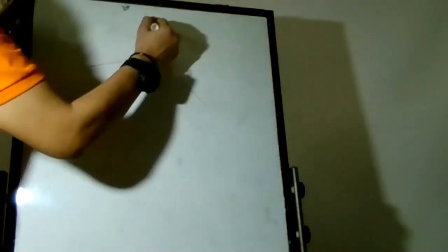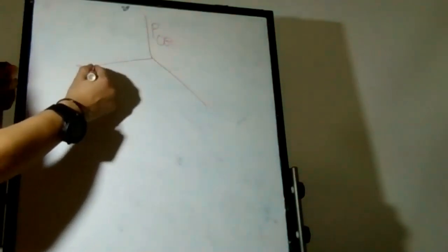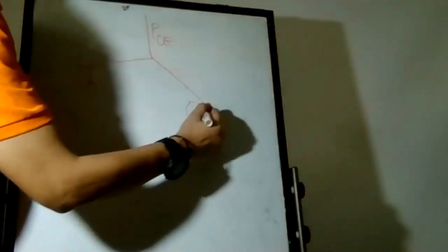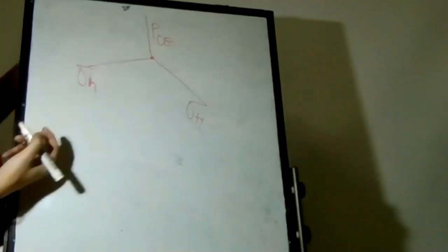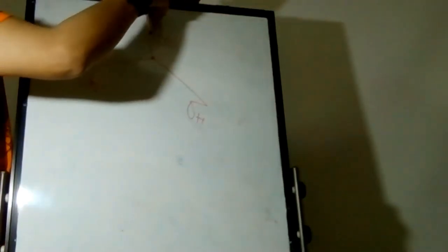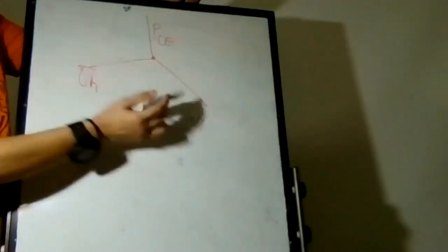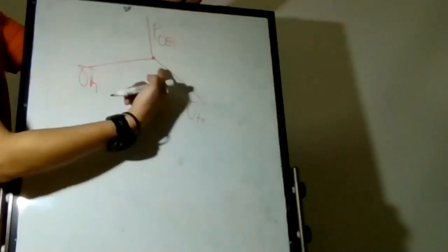There are three states of a stress. This is the state of a stress. This is what we call P overburden. And this is what we call minimum horizontal stress, and this is maximum horizontal stress. So at this point here, at the rock, you have an overburden pushing this way, you have minimum horizontal stress here and maximum horizontal stress on the other sides, perpendicular to it.